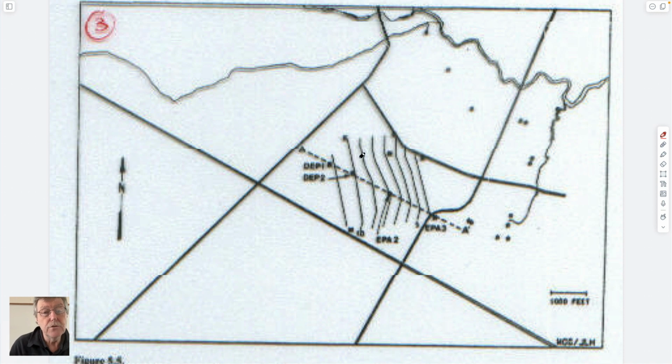At the same time, you can also go into the wells that you have. You've already done this actually, right? Maybe assignment 2, I can't remember. Take the wells that you have, and if you know the elevations of the water table in those wells, you could put a surface through those to say what the groundwater head contours are. So this is groundwater head contours of H equals whatever.